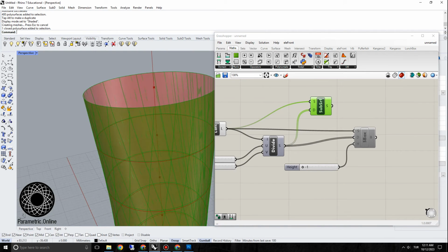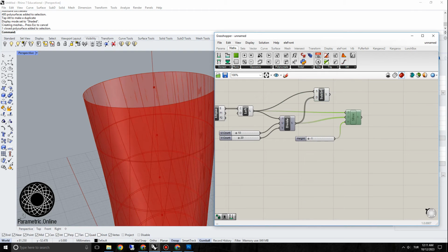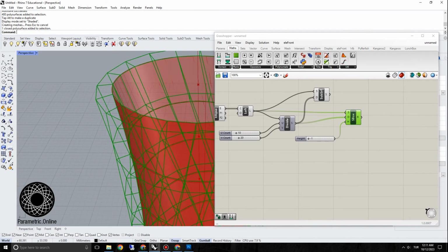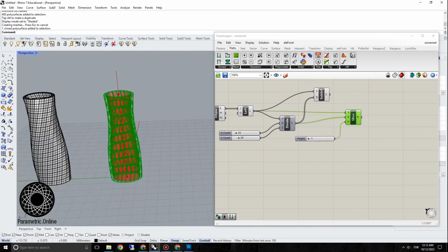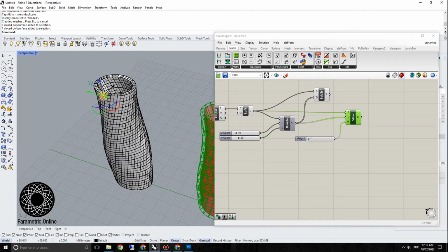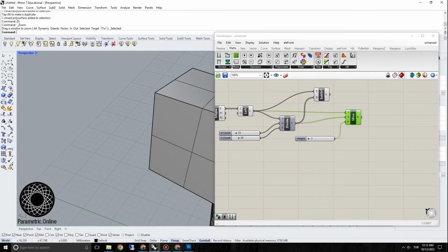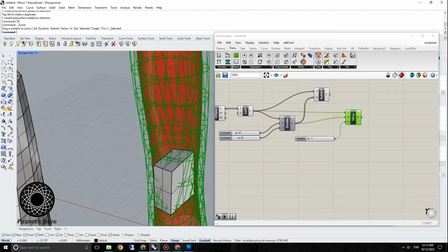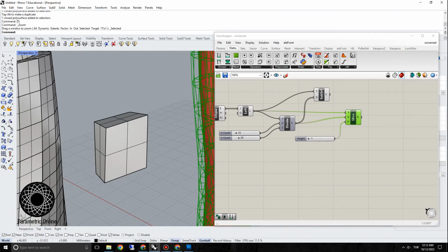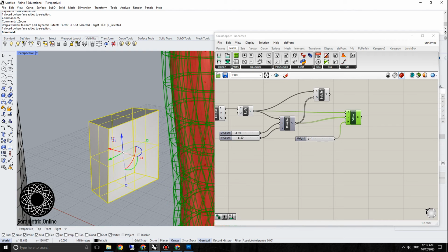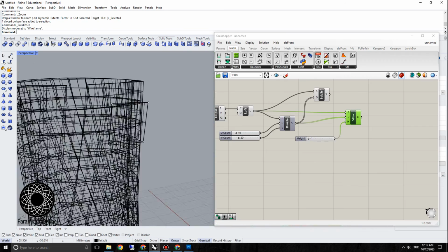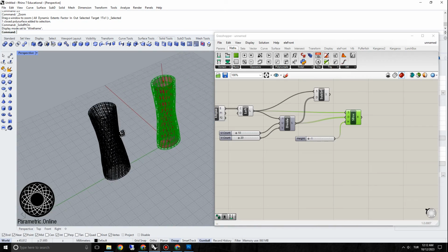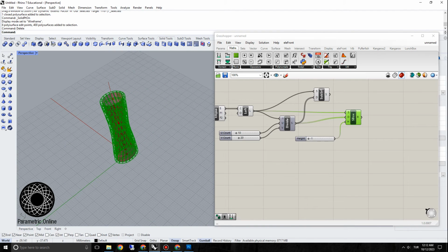So we can directly map something onto these panels, but what I'm doing is I'm actually doing surface boxes, which basically generates an offset cage here like this. Each individual one of these has basically a box shape. We call these twisted boxes, and this helps you to morph some geometry or some tile onto these boxes. If you turn on the solid points, you will see it has 8 corners like this, and using these 8 corners you can map some other geometry onto this. I'll show you what that does in a second.